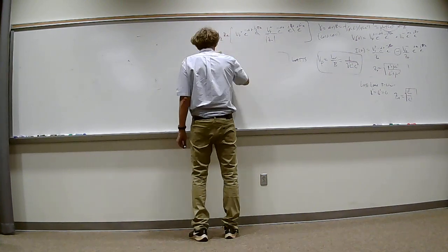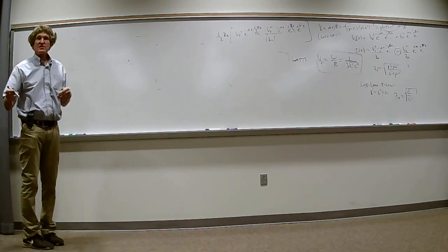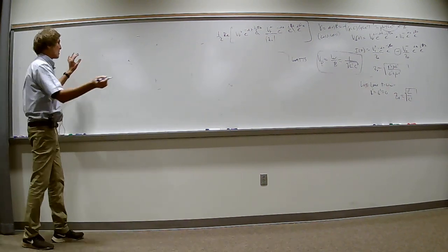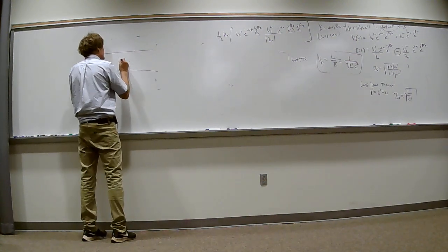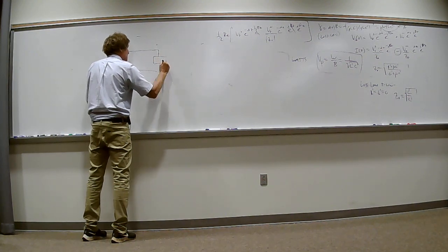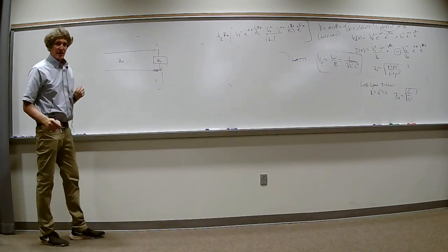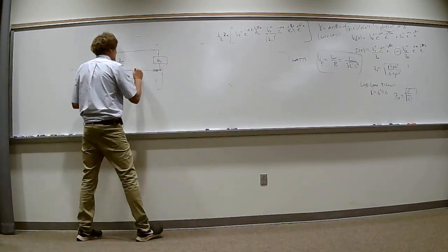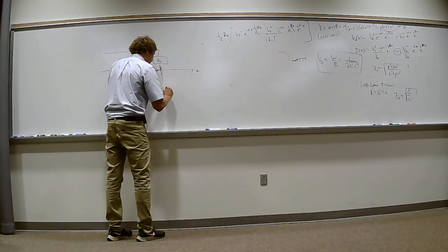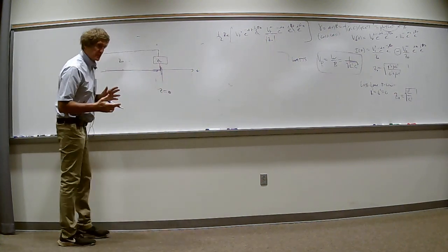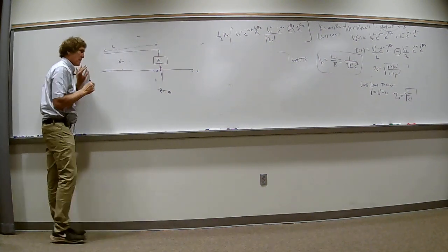So far we're just talking in generalities about propagation on transmission lines. They're not a finite length. We all know that a transmission line is going to be terminated into something called a load. So if you have a transmission line as such, it's got a characteristic impedance of Z0, and it has some load. To make things simple, we're going to use this as the Z-axis. We're going to put the load at Z equals 0. That's just the way we do business. Now we're going to assume the transmission line has a certain length, right here.